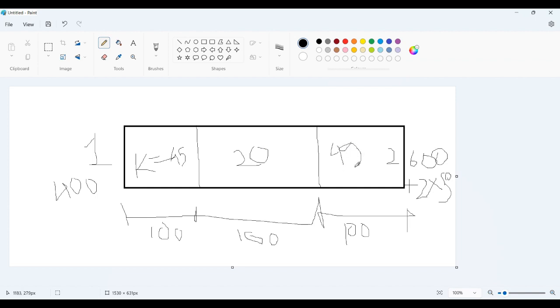Here, as we are considering the dimensional unit as mm, we need to divide this thermal conductivity by 1000 so that it will match our unit system.